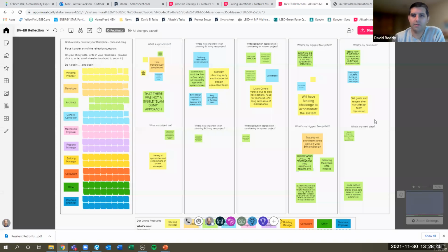Yeah, and one thing I want to reinforce is this isn't just Washington. It is most all of the major codes, ASHRAE, IECC, moving towards balanced ventilation with heat recovery as a requirement for these building types. We're a little ahead of the curve in Washington State, but within 2-3 years, it's going to be pretty universal.